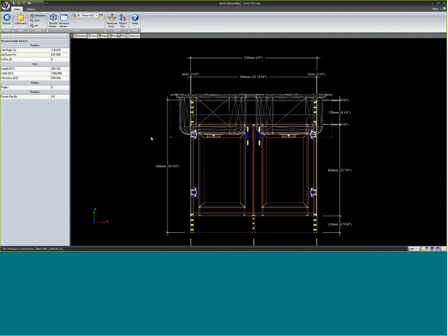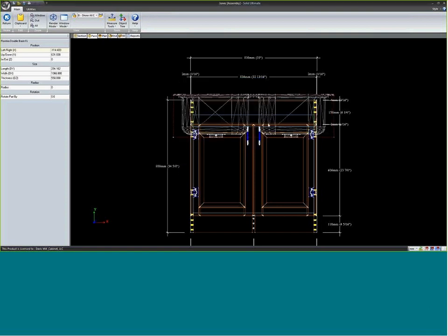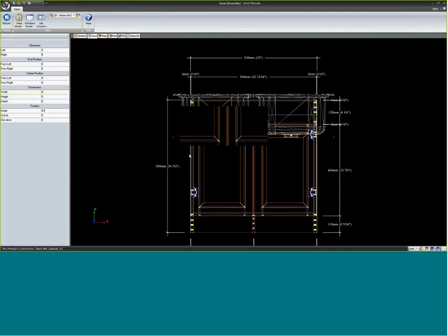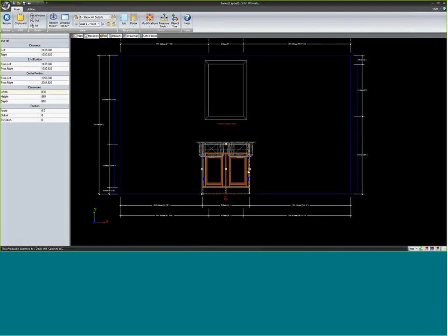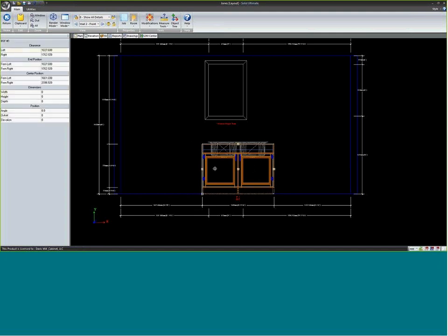So rather than change the width of the cabinet and then come back in here, I'm going to go to the left-right position of this sink now and use that equation I just used. The colon DX, the width of the cabinet divided by 2, minus the DX, or the width of the sink, divided by 2. Okay, so now it's centered in this cabinet. The nice thing about doing that method is that now I can come out here and resize my cabinet. My sink always stays centered in my cabinet, and when I move my cabinet, the sink moves with it.